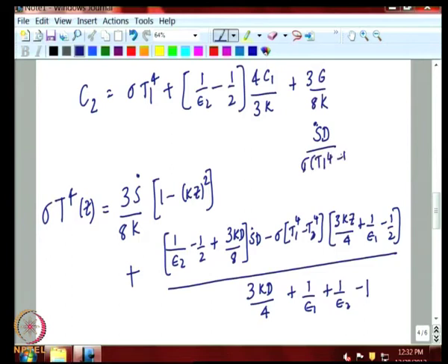This will determine the importance of this term. So, if this quantity is large, this term will dominate and we can essentially ignore this term. And in that limit, if the emissivity of the two walls is small, this will become large and this term will drop out, and you are essentially left with a very simple quadratic expression here.